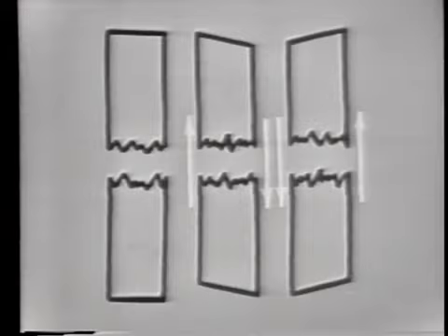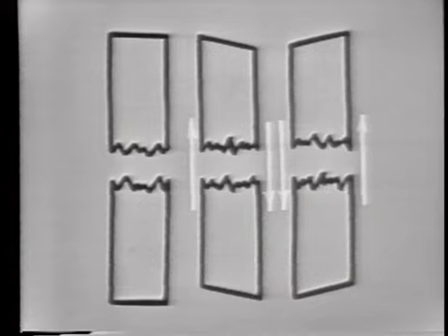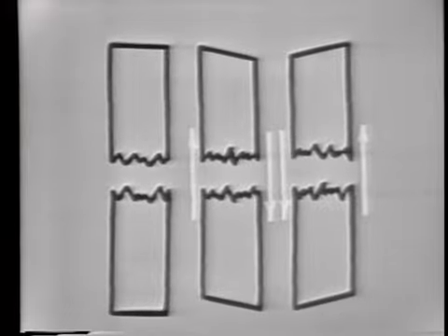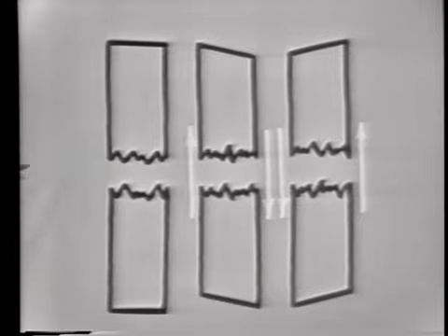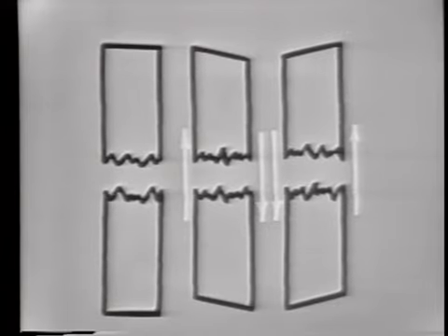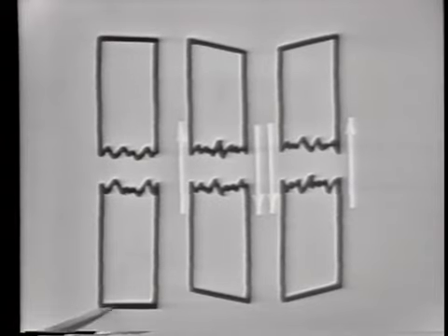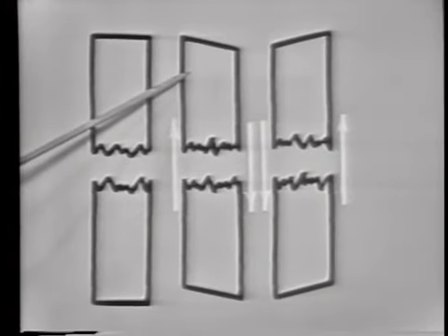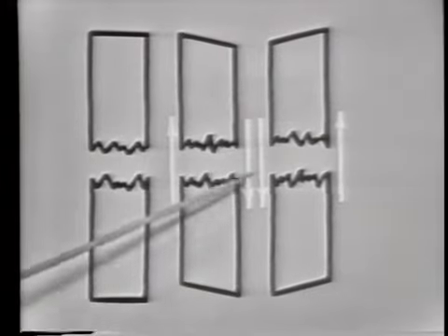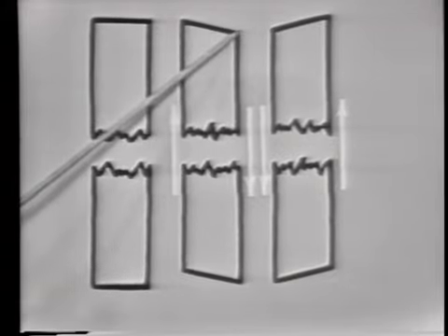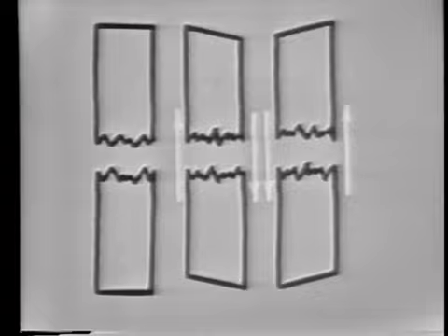You might ask, how is this accomplished? Simply by increasing the feedback to the point where the crystal is shocked into vibrations at the odd harmonic rather than the fundamental frequency. And let's determine what's happening when this is true. Here we're indicating the distortions that exist in the crystal when it's oscillating at its fundamental frequency. Here is the crystal at rest, no oscillations. Here the crystal is deformed to produce one alternation, and here it's deformed in the opposite manner to produce the other alternation.